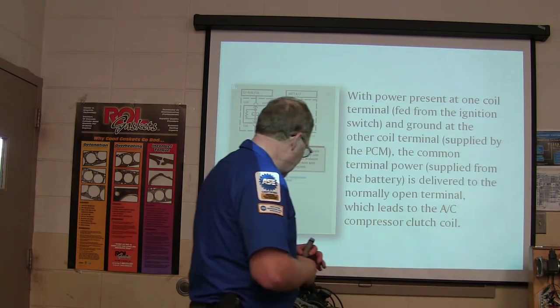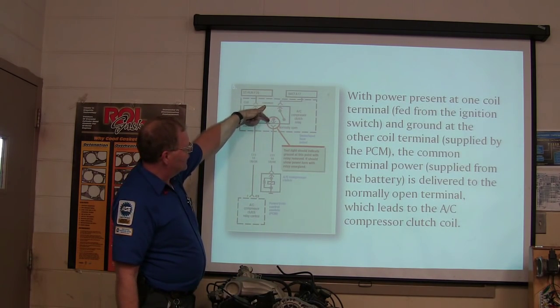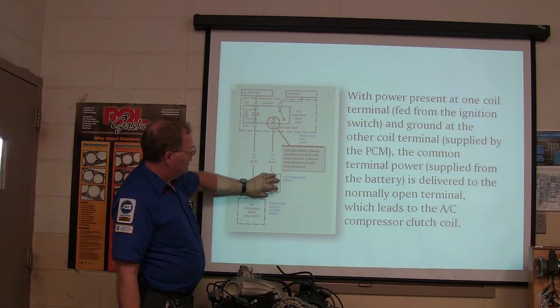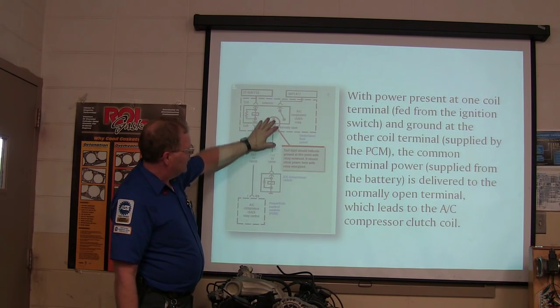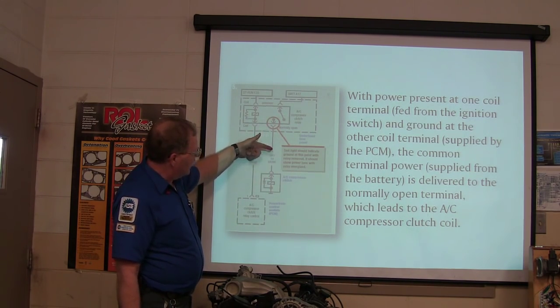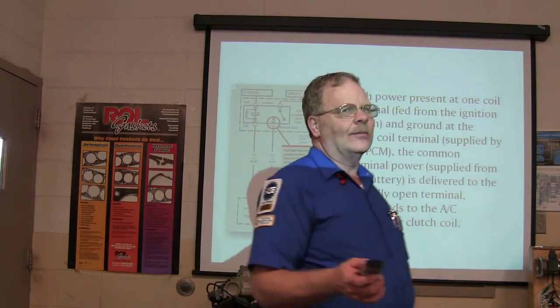What am I supposed to see here? If I connect the test light right here, where the relay is, and that light lights up with your compressor plugged in, then you know you've got a good path to ground through here. If the light doesn't light up, either this wire's cut, or you've got a bad compressor clutch. Now on that Nissan Altima, there was a bad compressor clutch.